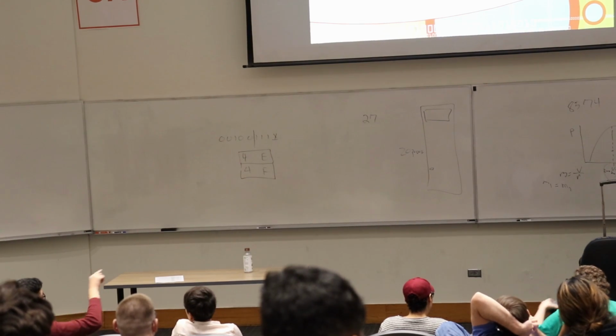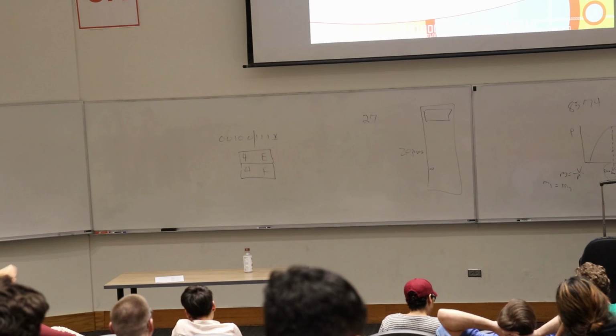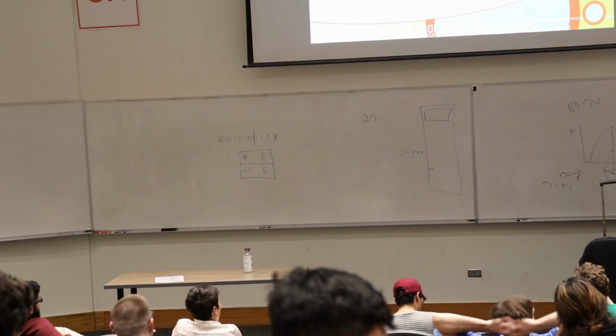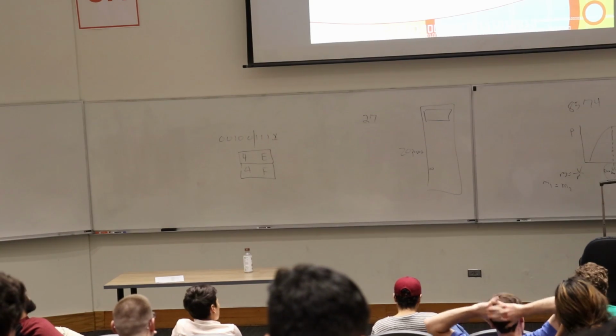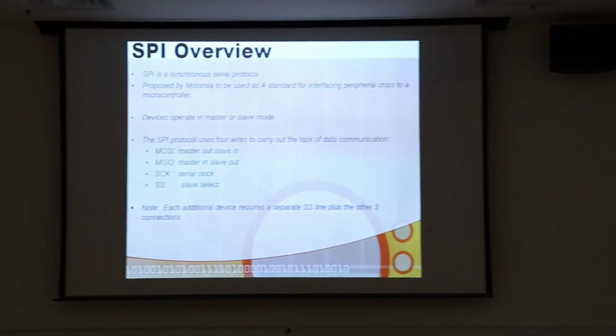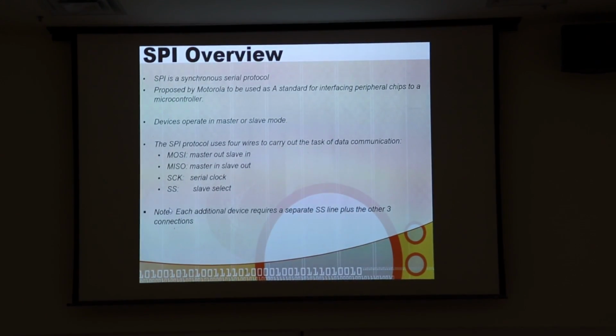In addition then, you have the clock line. Now the good news is the clock line connects to the clock line. So that's good. And the master is the only one that generates clocks. There's no screwing around with the clock. The slave can't do any clock stretching in SPI. And these lines are not open collector, they're hard driven.